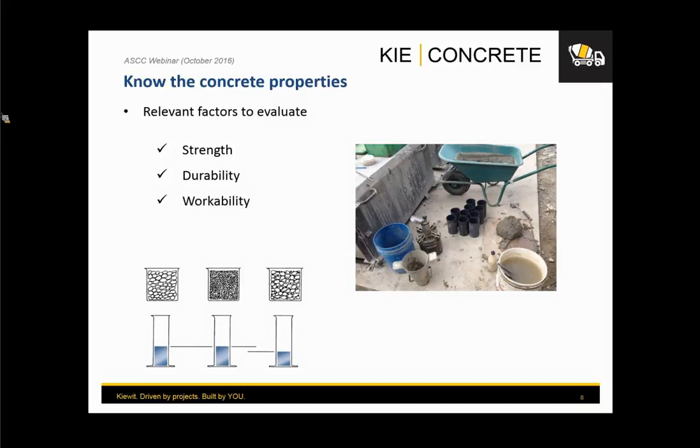Workability. Workability is as simple as, what does workability mean to you, right? It's not necessarily about the slump, right? You cannot just say slump is workability, right? There's a lot of discussion in the industry standards that slump doesn't mean workability, but then what does it mean to you? Is it something that you're going to place by conveying, or you're going to pump, or crane and bucket, or is this a slip form, right? You need to understand what operations you're going to implement in the field, and then what the mix requirements are to get the workability that you need.